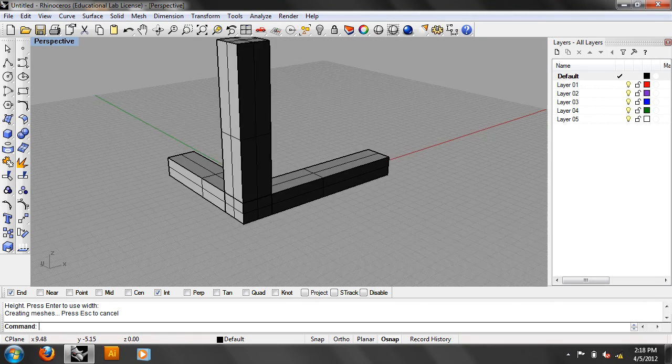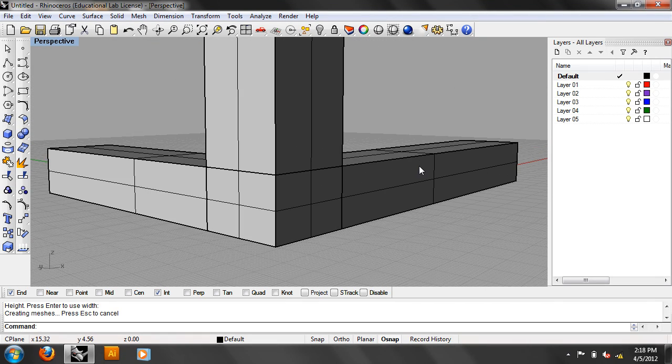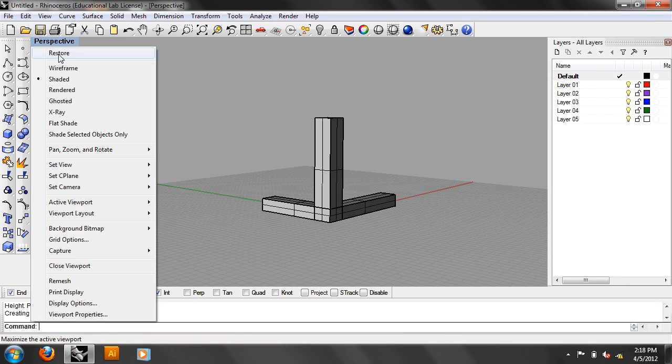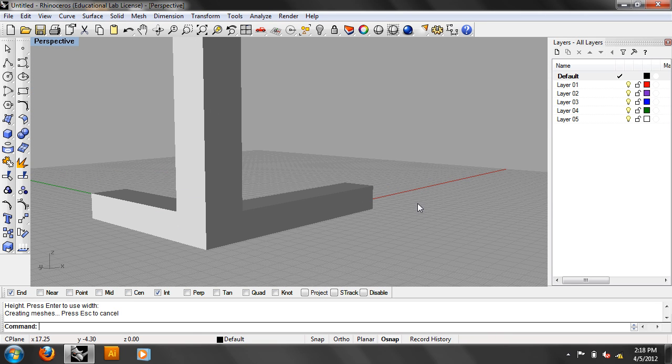Based on what I've talked about, what do we not like about this? There are three boxes inside each other, right? And in one place there are three inside of each other. So when we make 2D, we're going to get six extra lines, each one overlapping each other. It's not going to be clean. What we really want, in our mind, is something clean and pretty, but the geometry in the computer is bad. For all the reasons I explained, it's going to be hard to material, hard to analyze, hard to make 2D. We don't want that.